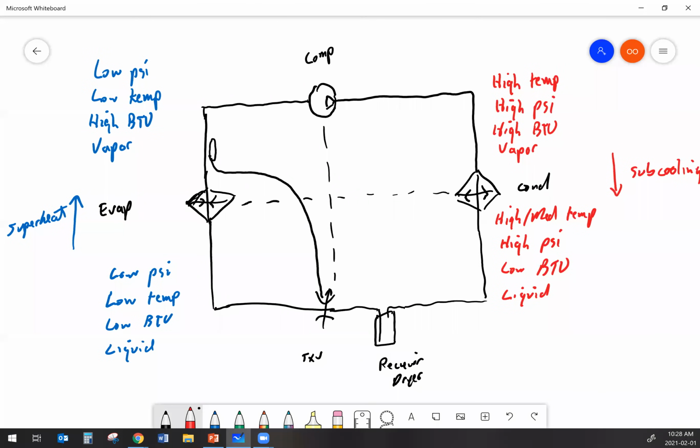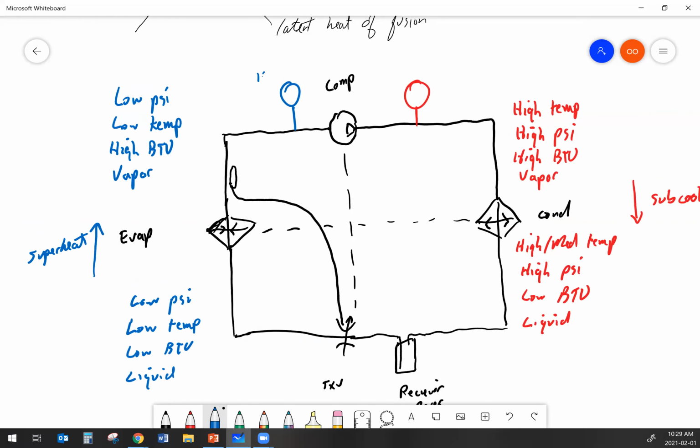So anytime you get a refrigeration system, you're also going to have service ports. And those service ports let you hook your manifold gauges up. With your manifold gauges, you measure your high side and your low side. And the pressures that you see on those, there's a couple of different numbers that you should be aware of. But in general, your low side, and here we're talking specifically about 134, under most operating conditions, we're going to be between roughly 10 and 30 PSI if the compressor is running.